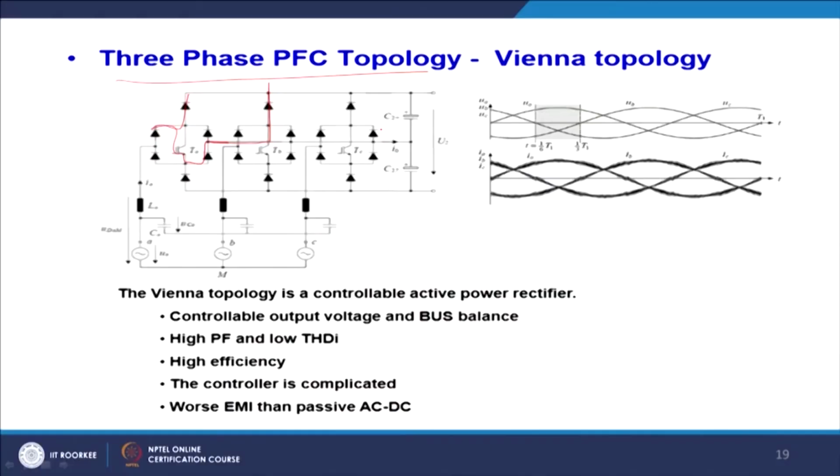So, you get 3 volt, and there will be a switch that also gives you around 2 volt; sometimes if it is a high rating IGBT, then a 5 volt drop will be there, and if it is carrying 100 ampere of current, each of the sets will give you 500 watt losses, you know. So, it is equivalent to running a 500 watt motor. Since you are not using it as a room heater, there is no purpose of having this kind of configuration,